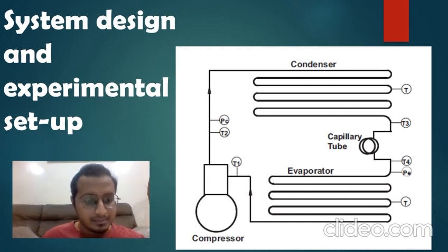The pressure at the inlet of the condenser and evaporator was measured in the refrigeration system before the temperature was measured. The surface of the tube was polished, removing any dust or rust, and then the thermocouple probe was laid down on the surface in order to reduce the thermal contact resistance between the thermocouple probe and the tube surface. Thermal grease was used at the point of contact.